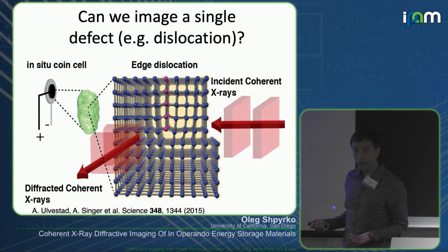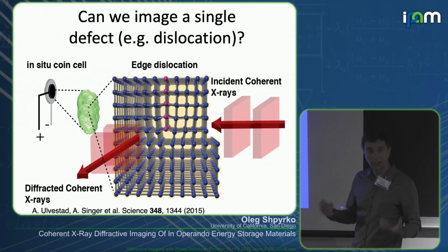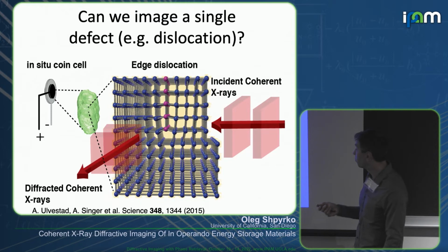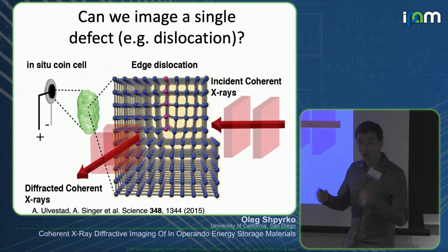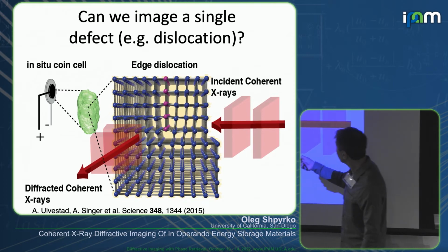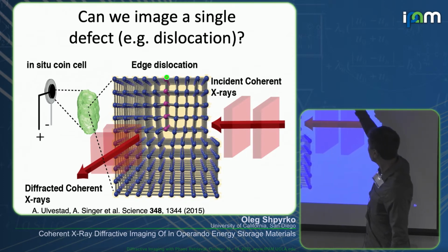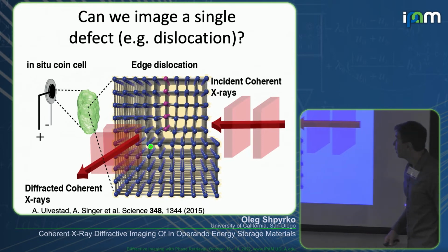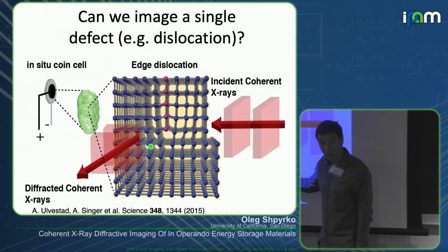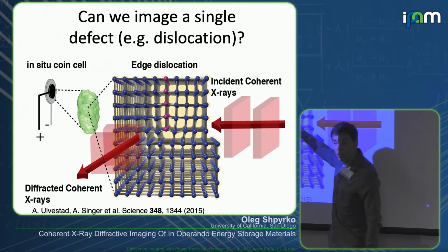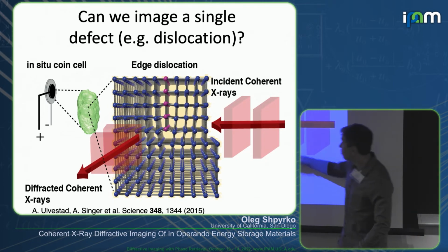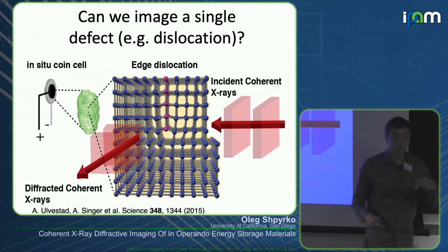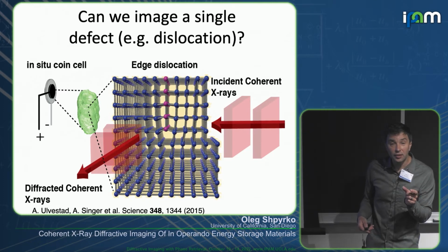can form dislocations, and this is just, again, for those of you who haven't taken material science or haven't taken it in a while, you can think about an edge dislocation, for example, as simply taking a crystal, which is perfectly well ordered, and then inserting a half plane of atoms here, which basically creates a topological defect, because if you're a little guy walking inside of the crystal and counting your steps and trying to come back to the same point, anytime you go around the core of the dislocation, you'll be displaced by one unit cell, right?